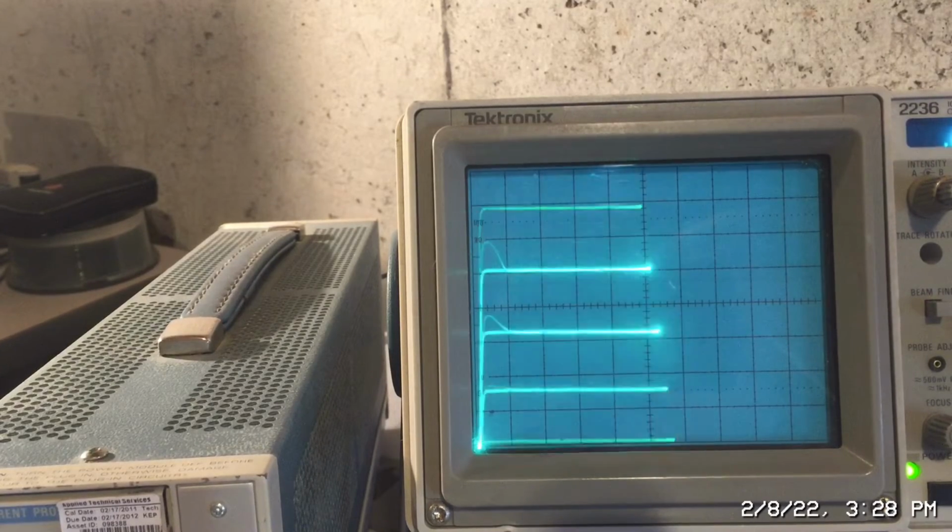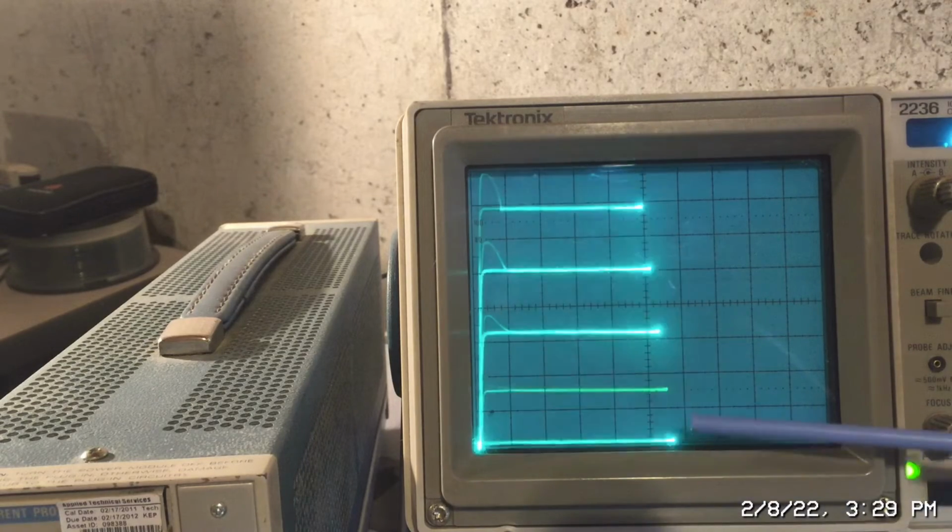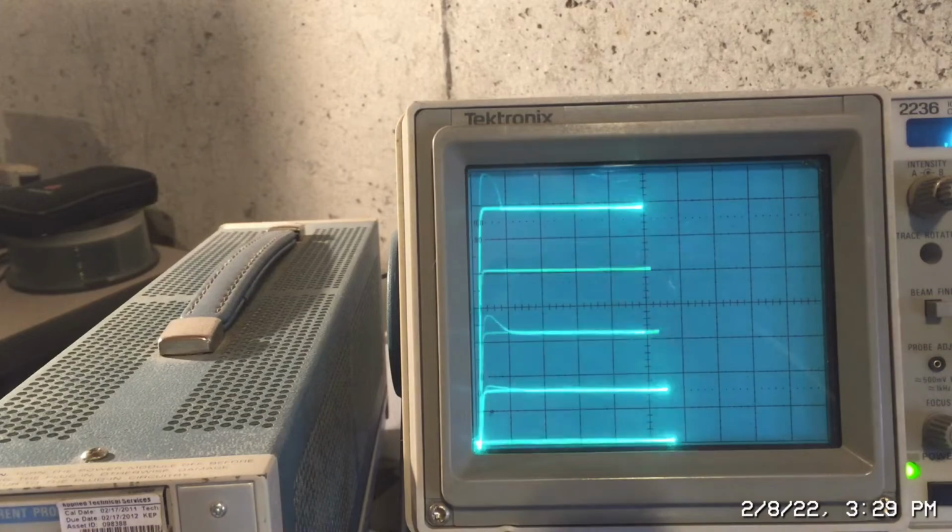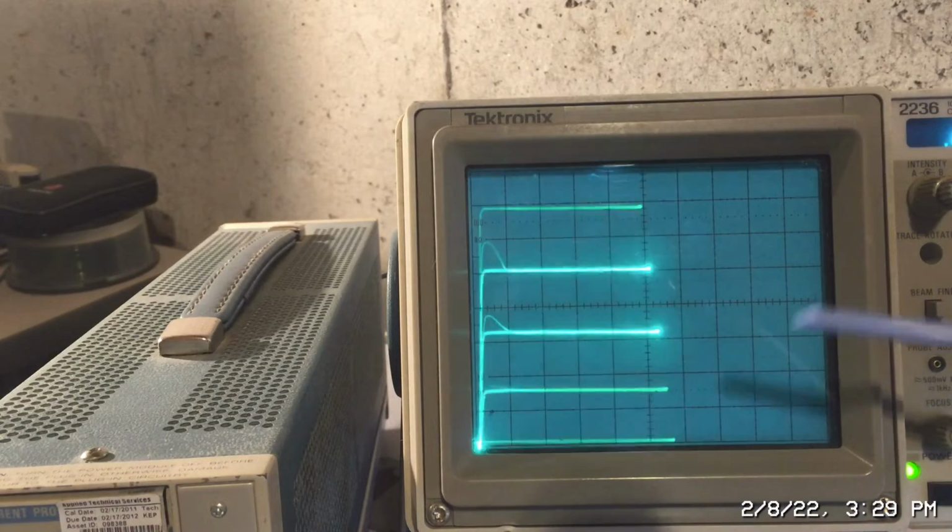3.5 milliamps divided by 200 microamps, I'm looking at 17.5. Okay, and what did the spec say? Somewhere between 10 and 40. So it's reasonable. One thing to point out here that you can see in the baseline transistor that we had